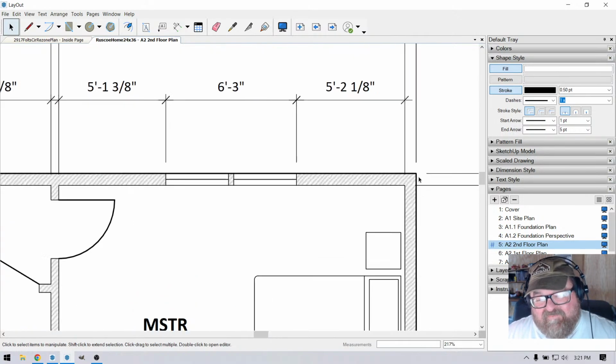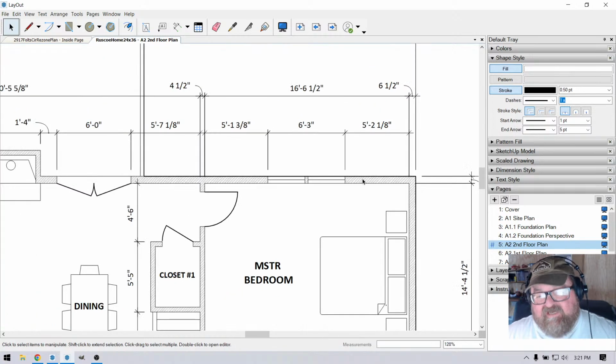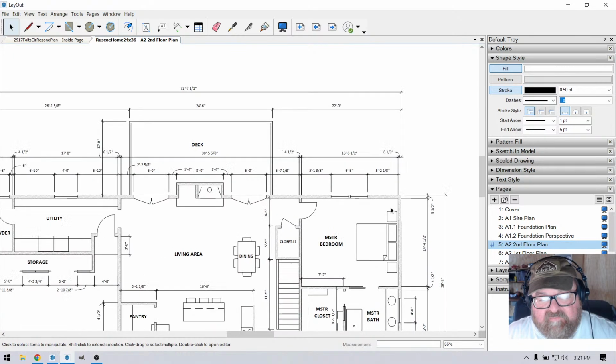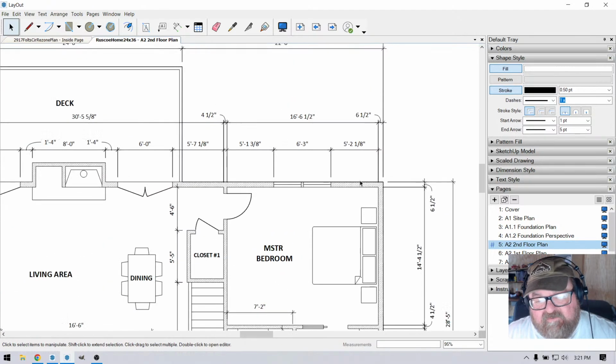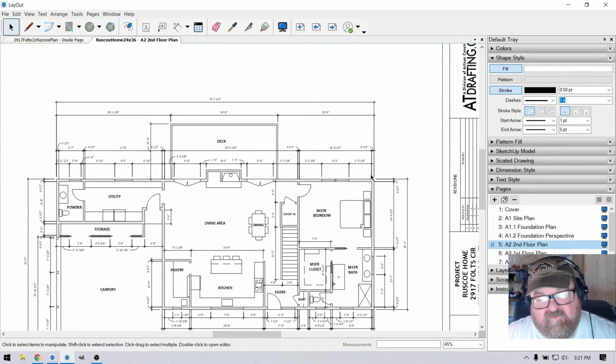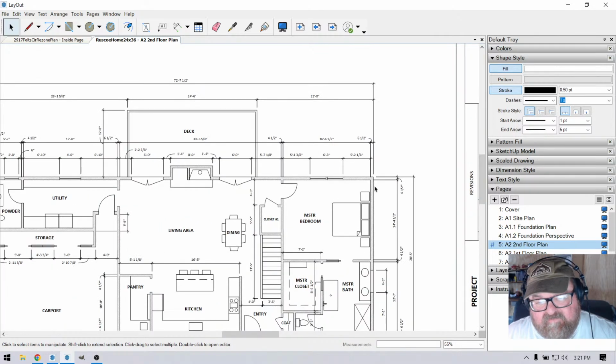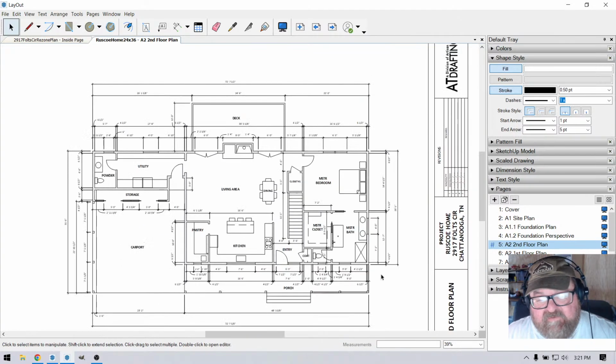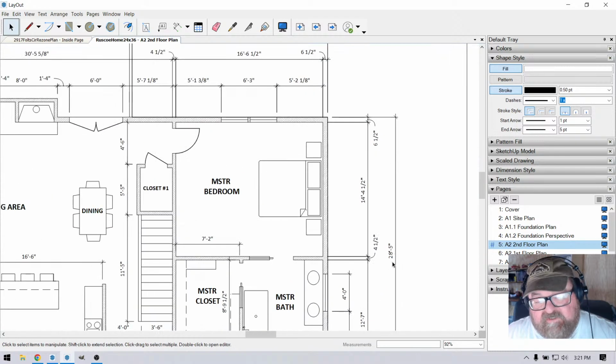So we say no. We always use the standard. You see, if we stick to a standard, we all don't have to guess. And this is another reason why it's important. I'm going to keep adding layers to why this is important. When you actually start building your house, the framer's going to want to know where the house line is. And so this is how we dimension. We dimension to the house line.